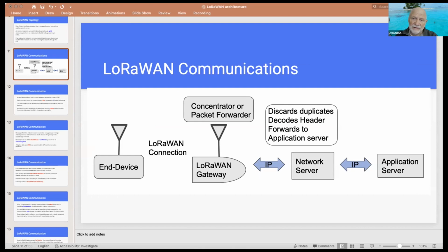Especially, for instance, if you want to have a meter in the basement of a building, then you need a high power budget in order to traverse the floors and the walls of the building and still get a reasonable signal. These requirements are not really met by Wi-Fi and legacy cellular technologies because they were designed for short range and high bandwidth, which is not normally the requirement for IoT.